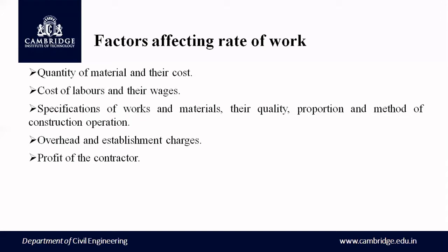It is about 6 to 8% of the project cost, and includes the indirect expenses incurred during the execution of a project. That is, the first one is general overheads, and the second one is job overheads. Under general overheads, there will be establishment overheads, stationery, printing, postage, travel expenses, telephone, rent, and taxes. These are all general expenses.